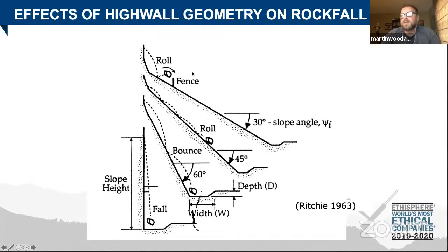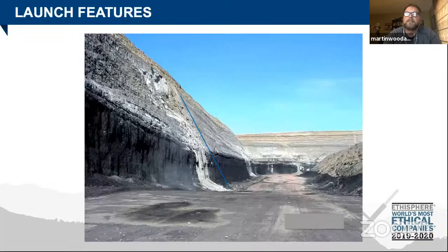So you only have a range of generally between around 35 degrees and vertical where the rockfall is really a big hazard. So you start to take a look at the trajectories of rockfalls as they come down and be able to predict these things. As the rock starts to come down, you have this idealized thing. Let's see here. I have this slope and it is coming down, and so I'm going to expect to have rocks falling out into this particular type of area.